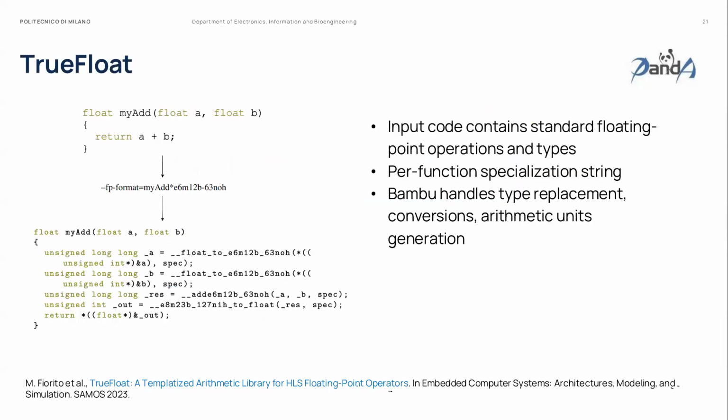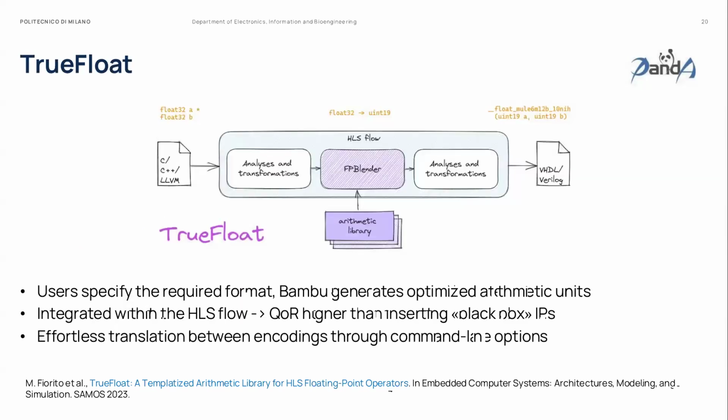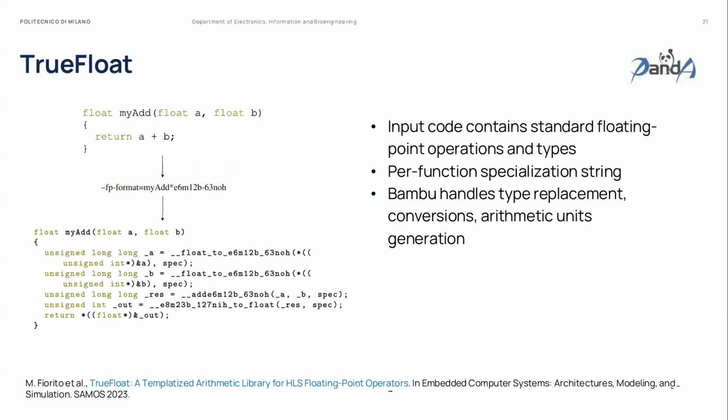So how do you implement this? This is also in C++, and you convert it to SystemVerilog? Yes. And then I guess it's only floating point. You cannot do bfloat or posit or other formats. Bfloat, I think we can do, because bfloat can be expressed as a combination of exponent, mantissa, etc. Posit, no, because it's a different encoding.